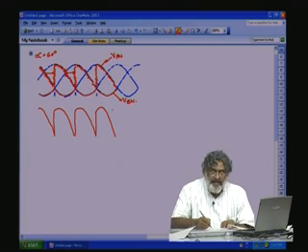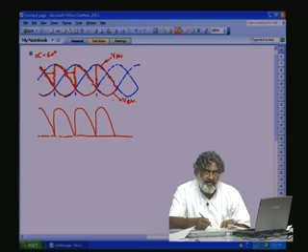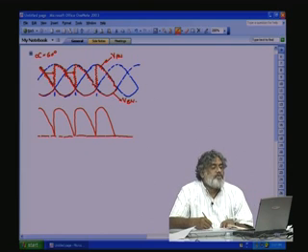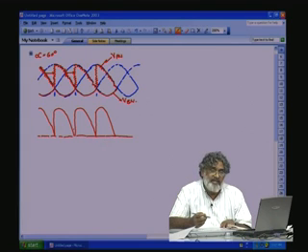Here if you see, this is the 0 line. At alpha is equal to 0, the ripple exactly comes to the 0 line and then switches. But if you see here, compared to the fully controlled converter, the semi converter ripple is 3 times the mains, but for the fully controlled converter it is 6 times. So the ripple content of the current will be much less in a 3-phase fully controlled converter compared to a 3-phase semi-controlled converter, that means with thyristors and diode. So this is 60 degree.